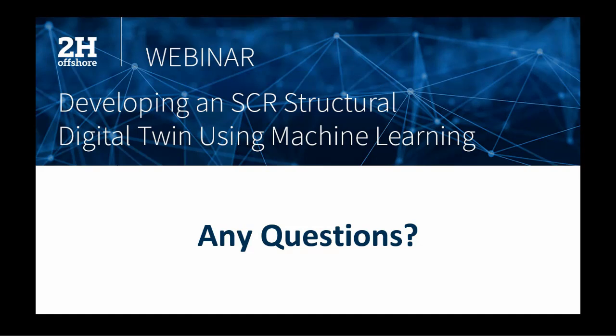That's a good question. How do you reconcile simulated data with real data as the machine learning model input? One of the important parts is that the input data for the FEA model as well as the ones that you actually obtain for the measured data need to be identical. If not, it needs to be modified so that it is as identical as possible. Once you have that, you have to use suitable data cleaning. That way, we basically ensure we have a robust enough time trace as input information before you parse it through any of these machine learning models. That's how we reconcile it.